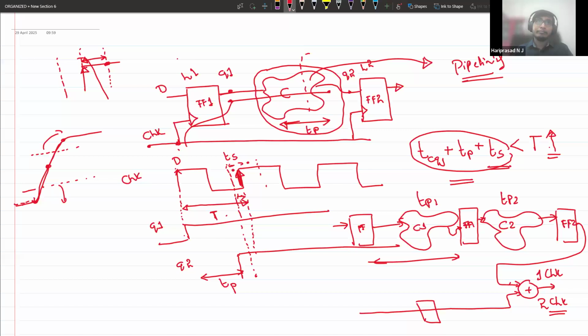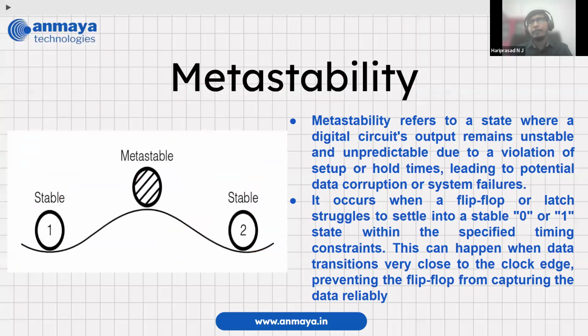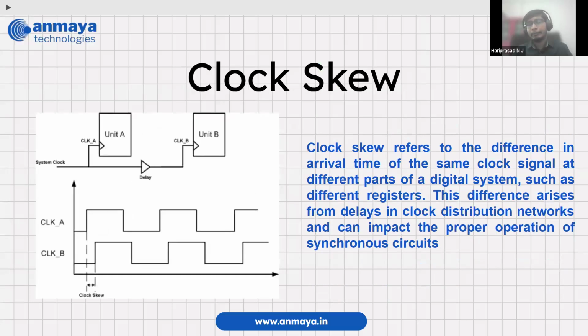Okay. In FPGA, even though in simulation you will see high impedance or undefined, inside the digital logic I cannot have high impedance or in-between voltages. Theoretically we can say it is undefined or a metastability state, but it can go either low or high, right? So your whole architectural logic will go wrong in these scenarios. The main impact of setup and hold time violations is basically metastability. Okay, so basically you are spoiling your data.